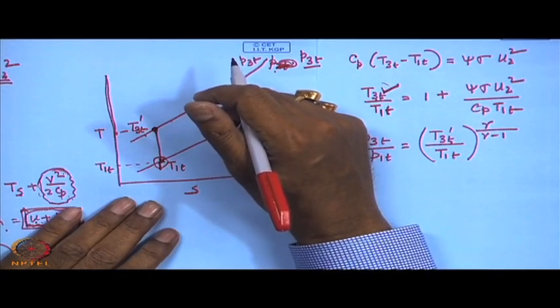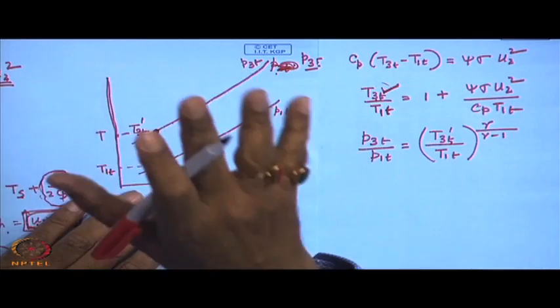As we know, in an adiabatic process, that means a process without heat transfer, but with friction or internal irreversibility, entropy always increases. What is an isentropic process? Isentropic process is a process which does not have any heat transfer with the surrounding. At the same time, there is no irreversibility inside. There is no friction. Temperature is almost uniform at any instant, so that internal dissipation or internal irreversibility is 0. At the same time, there is no heat transfer, so external irreversibility is 0. So, the process is totally reversible and at the same time adiabatic, so entropy remains constant, that you know from thermodynamics.